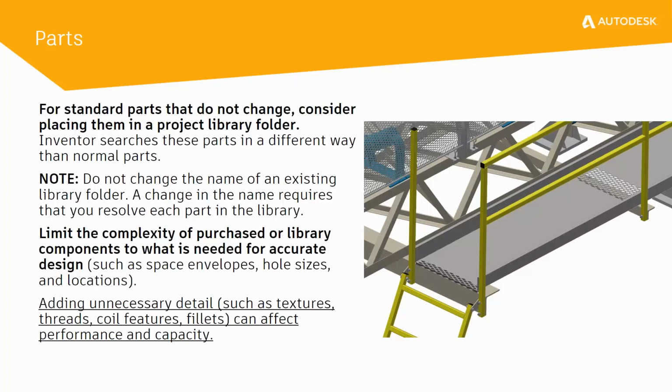Here on the image on the right, you can actually see two unique ways of applying the detail of the mesh of both the walkway and the guard around the outside of this piece of machinery. In one instance, the designer has actually gone through the process of modeling small sections of expanded mesh into the design, but not the entire length of that section.